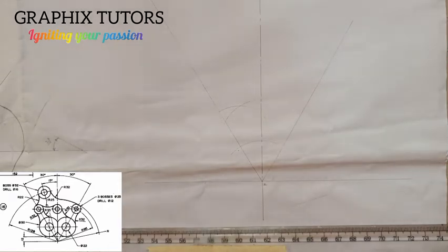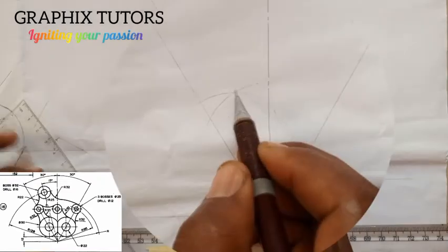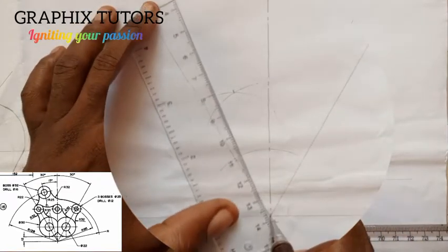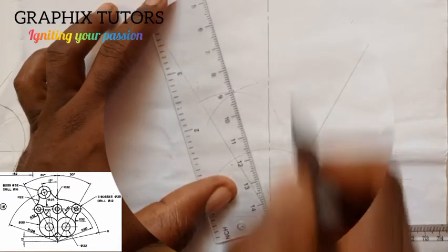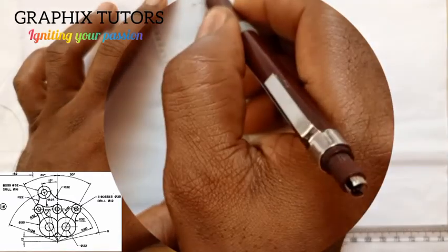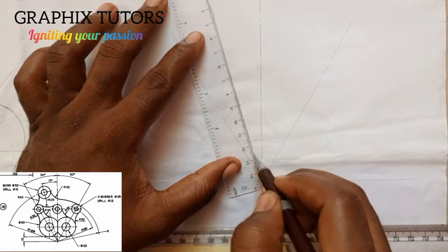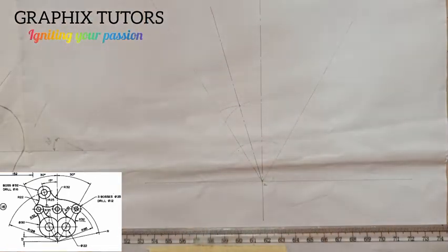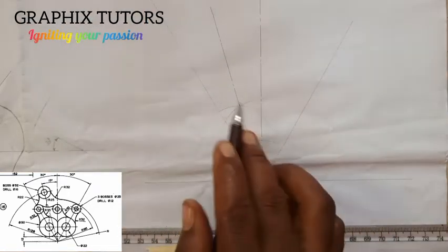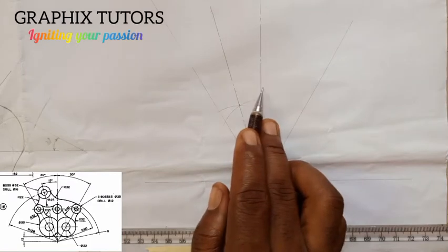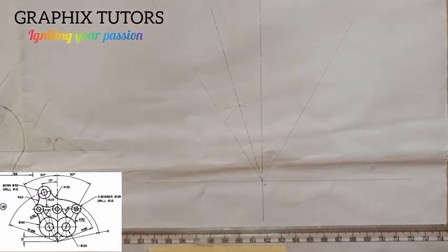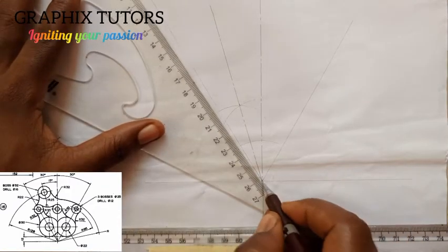Now I'm going to draw a line that will pass through that point I intersected. So that line should be a center line. So I have this long, short, long, short, long, short, long, short. This is what we have here. So it means that the angle from here to here is 15. And also this should be a center line. They all should be a center line, not just an ordinary line.